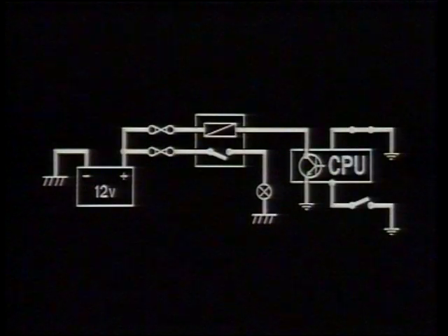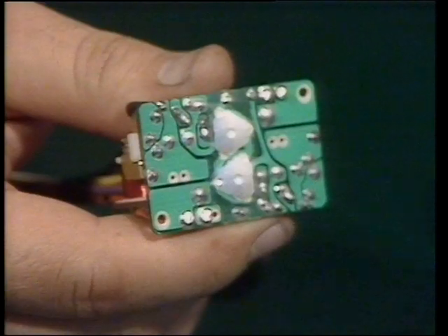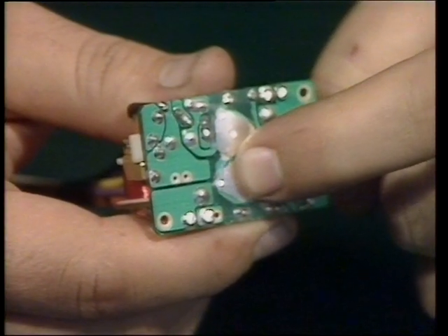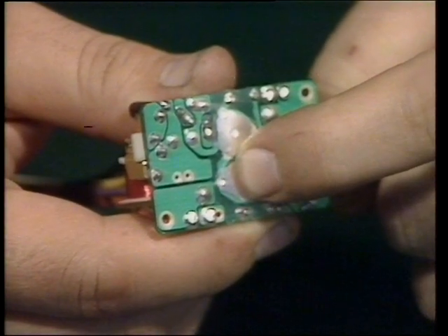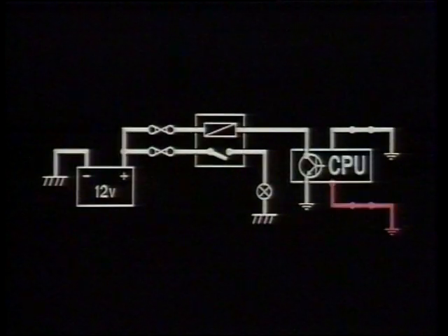In circuits of this type, momentary action clicker plate switches can be used. Their contacts are much smaller than those needed in circuit 1 because they only need to carry the minute current to signal to the CPU. This circuit is activated by this switch.